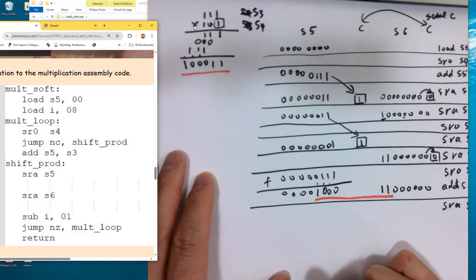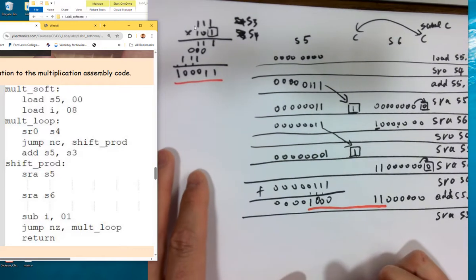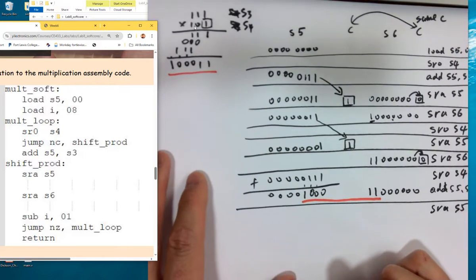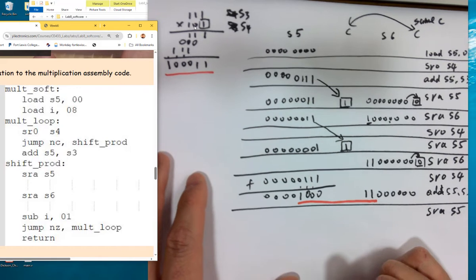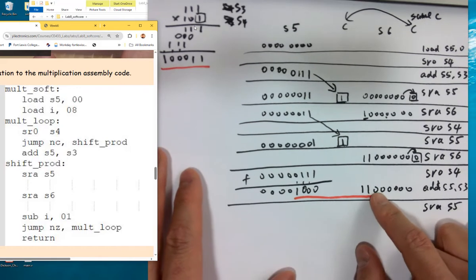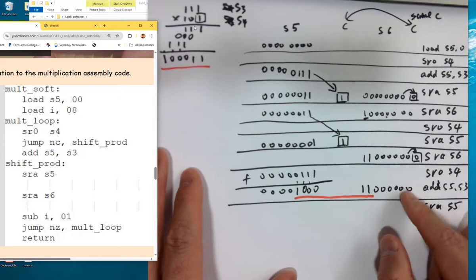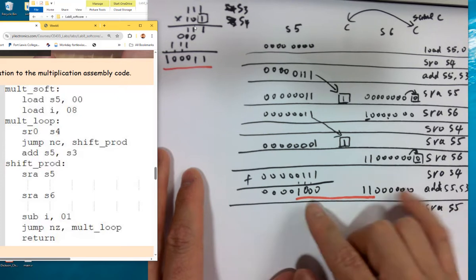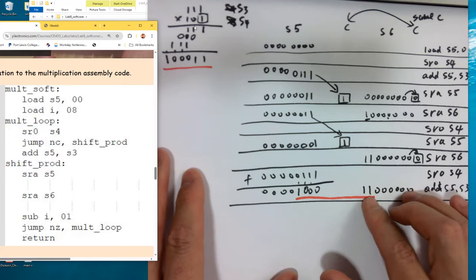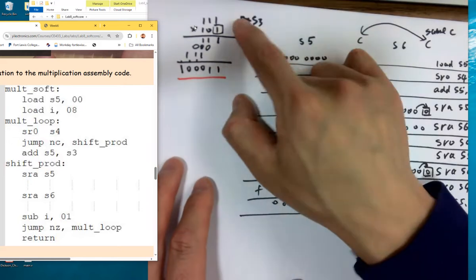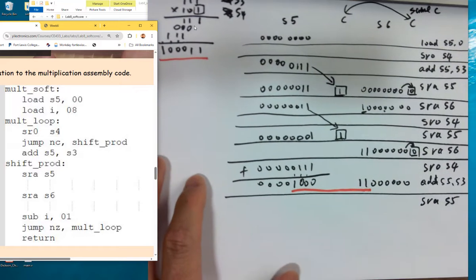So it's gonna shift for how many times after this? 6 more times, right? You can see the count of the zeros over here is basically 6 zeros. And eventually shifting for six more times will shift everything to the lower byte. And that's the final product of the multiplication.